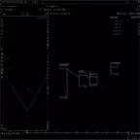So if I now connect the noise to this value port and the value port to CD, nothing happens because the ranges are identical. But if I change the source min to -1, I now map everything to the space between 0 and 1. So I normalize the noise, which is looking a lot better. But I not only can use noise for shading or for setting the color, I can use it for a displacement effect too. For this I have a node called displace along normal.